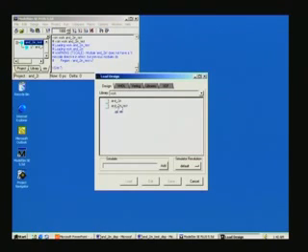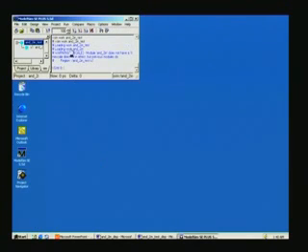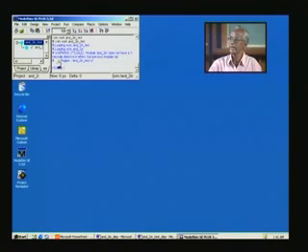Then you have this is the top test bench. So double click on this and load. Now you see there's no error, but some warning is given. This is a trivial warning. You can ignore it. What it says is module and2in does not have a time scale directive in effect, but previous modules do. The previous module is the test bench that has a time scale we have already given, but it is not mentioned in the design as such.